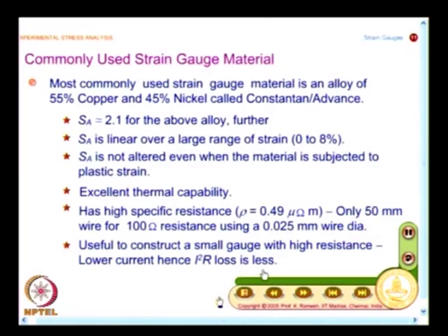See, I said in all strain gauge instrumentation, you will have to keep looking at the thermal influence. When current passes through the conductor, what happens? The conductor gets heated up, and you call that I squared R loss. And if you have looked at my statement very carefully, I had said with the advancements in composites, people have developed 300, 350 ohms, 500 ohms, 1000 ohms, 3000 ohms, etc. And whatever heat is generated on the strain gauge has to be dissipated away.